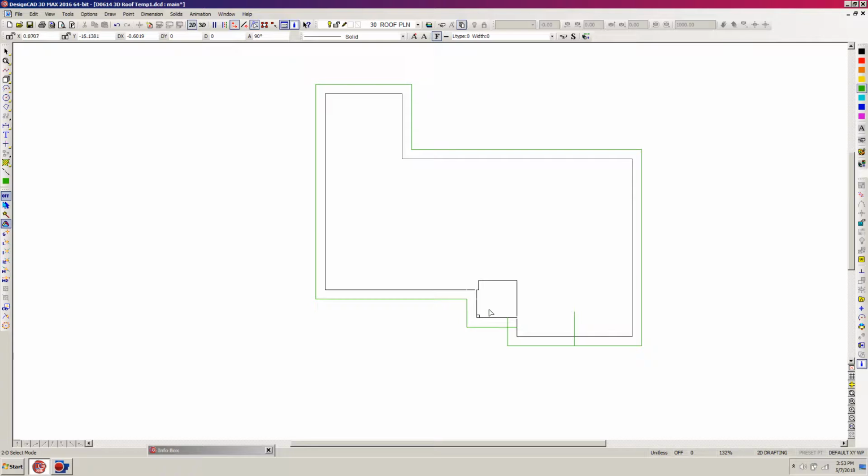And then I'm going to need a larger ridge, because this is going to span all the way over to this other side. So I'm hitting V for vector and just hitting K here and K over here. I'm still in orthogonal mode, doesn't really have to be. And then I'm hitting my scroll button to initiate the command. And so this one I hit V for vector and Control K. H for orthogonal mode. I found my ridge. So I'm going to go on up past the midpoint here a ways and hit enter.